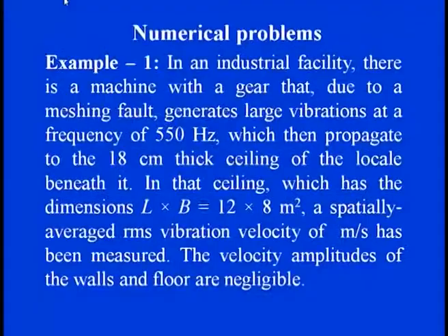And you see here the air which is being circulated there, we can take the specific impedance as 400 Newton second per meter cube. So, these are the input parameters which directly interact with the machine, and you see when this vibration is propagated, we have the ceiling which is 18 millimeter thick, and then all these dimensions are there.